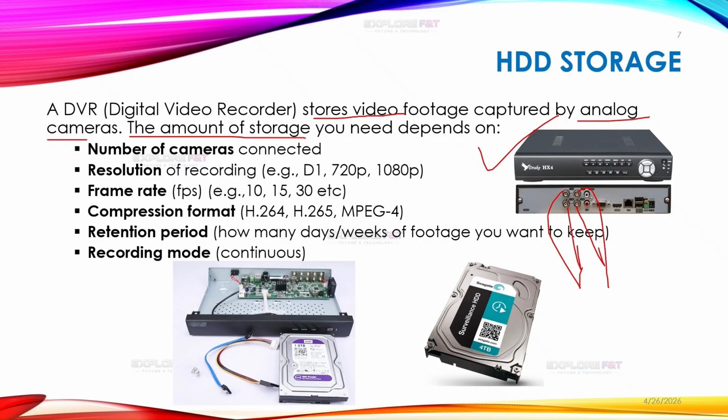The amount of storage you need depends on the number of cameras, resolution, frame rate, compression format, retention period, and recording mode. These are the parameters that could affect the hard disk storage. We have to consider these factors before choosing any hard disk for the DVR.